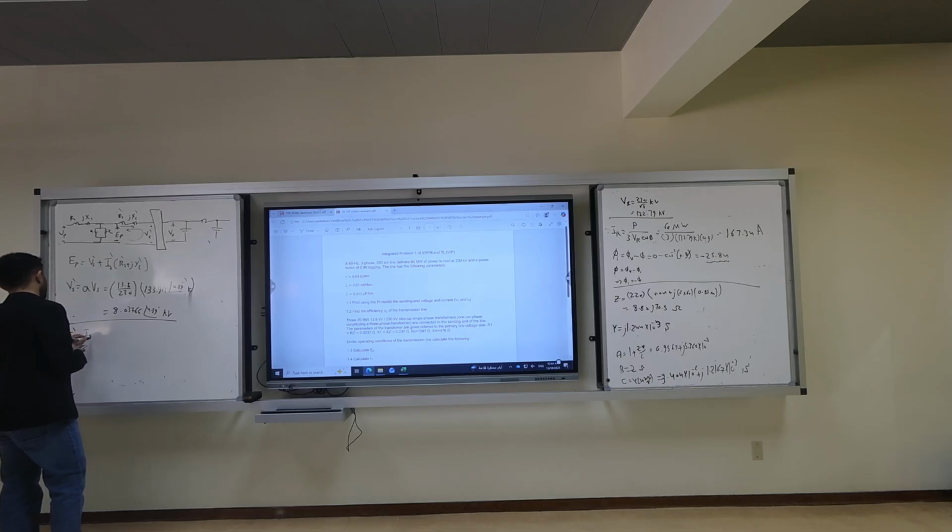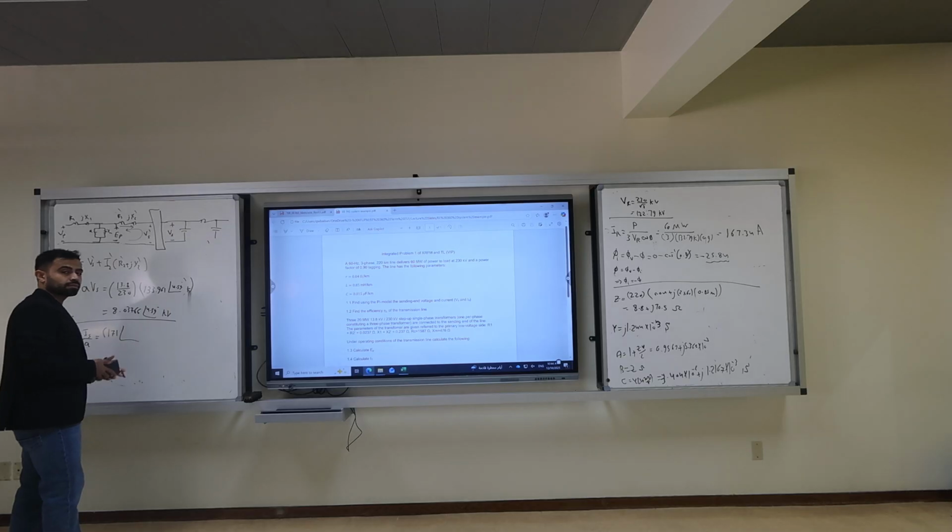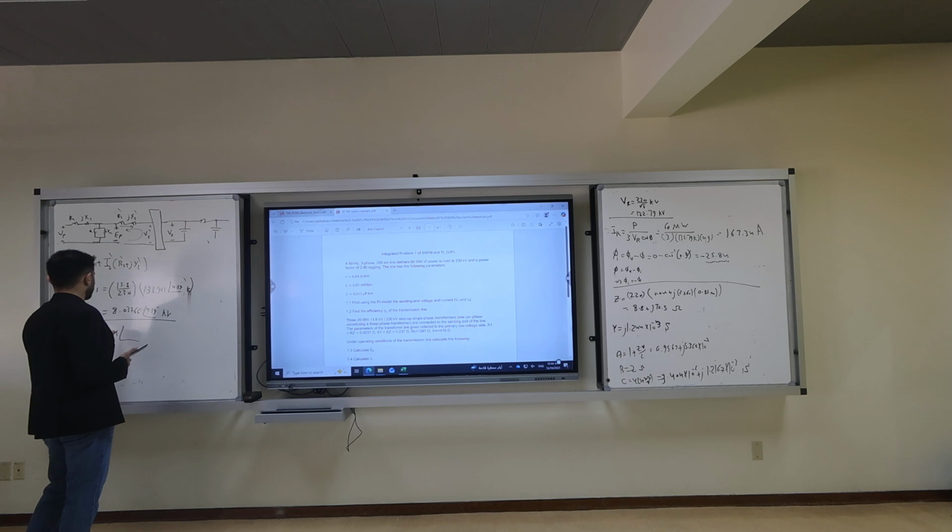It is IS over A, right? Which is IS? 171.24 angle 32.73, divided by A, which is 13.8 over 230. 171.24 angle 32.73 divided by 13.8 divided by 230.